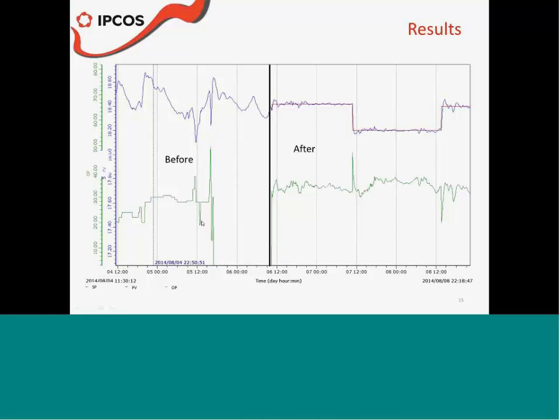This is what you see here: basically them trying to put the old configuration in automatic, in which the pressure was controlled by the inlet guided vanes. You see how the response is very big and the regulation is very poor. And after we did the study and implemented the new strategy, well, it just shows it's very smooth control, very tight control.